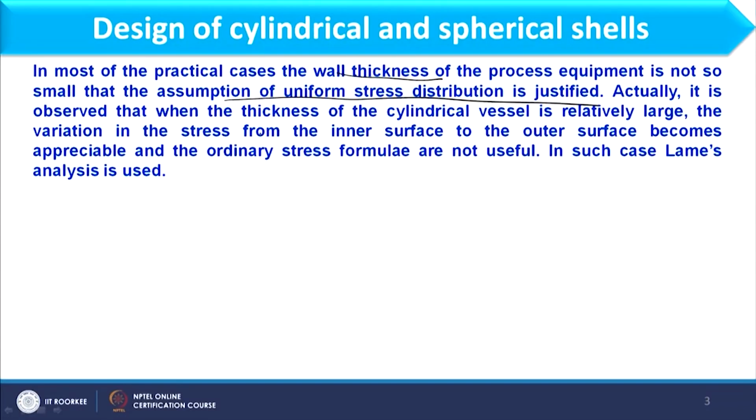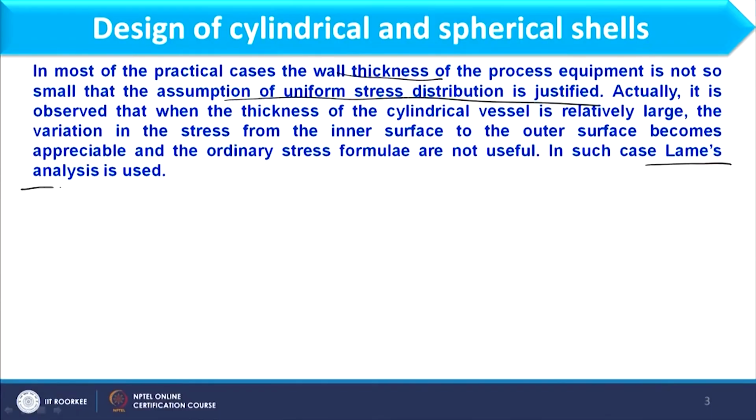So when I have a thick walled vessel, whatever expression we have derived for membrane stresses will not be applicable. So to design the thick walled vessel we will use a different analysis, and that analysis is known as Lame's analysis, as it is mentioned over here.